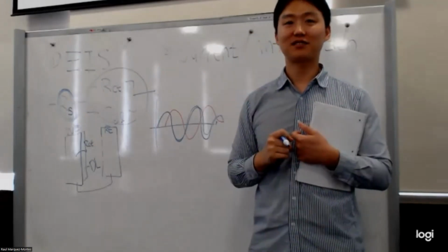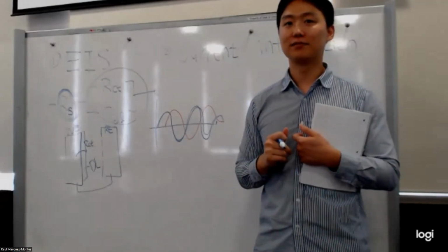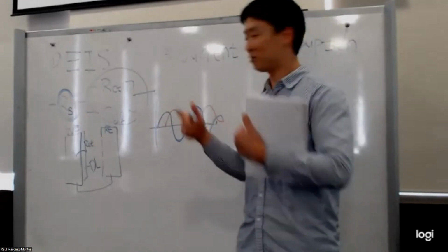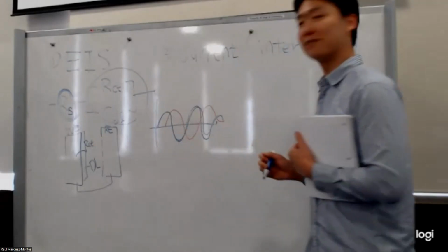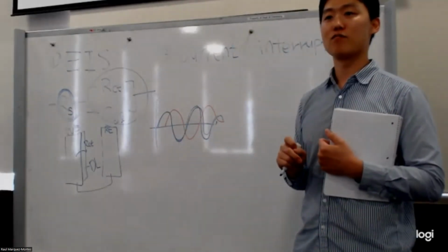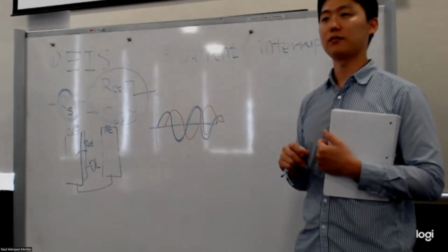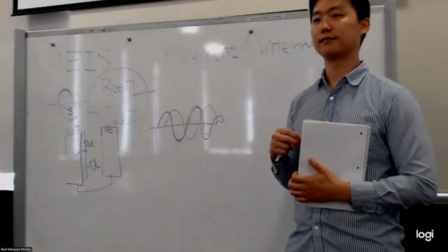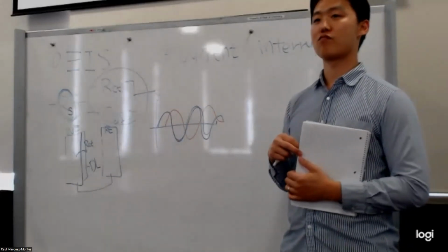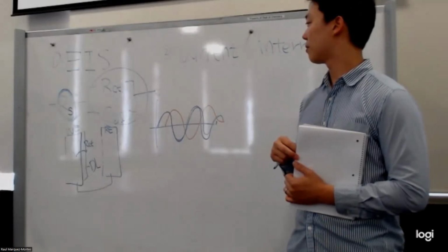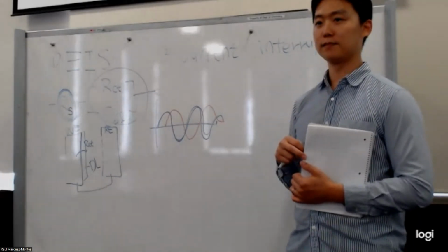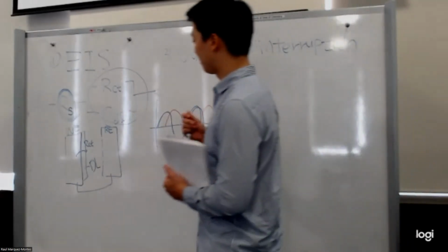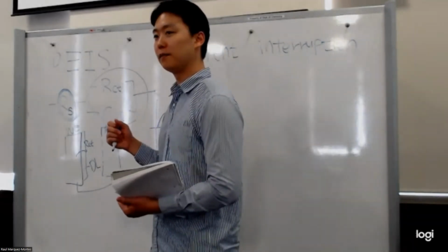Yep, go ahead. So the RS will be equal to RU? Yes, here we can consider RU is the same as RS. Sorry about using two different terms. Could you please repeat once again? So we seek to obtain the uncompensated resistance, which is the resistor on the left, and that's in series with two parallel circuit elements, the charge transfer resistance and double layer capacitance. So under what parameters does that second circuit element, the combination of RCT and the capacitance, vanish, so that we just get this resistance?